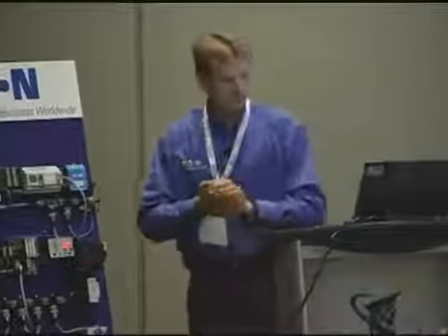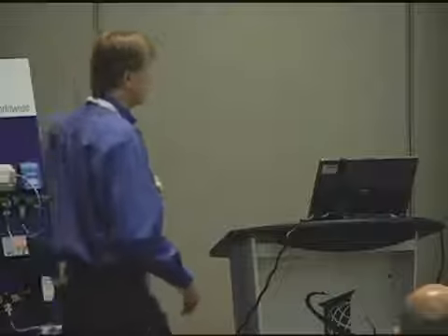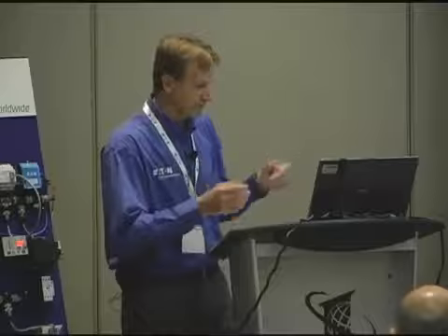Okay, so here's an example of some of the governing bodies. As an example, Modbus. If you go to their website, modbus.org, it has all the documentation you need to implement, and you can also join as a member. And it also lists all their members. Okay, DeviceNet and Ethernet IP, they're governed by ODVA, Open Device Vendor Association organization, and I put one in there on the bottom, Profibus. Now, Profibus is somewhat of an open/proprietary protocol. There's different flavors of Profibus.